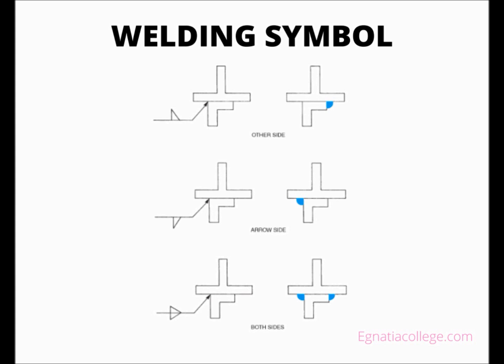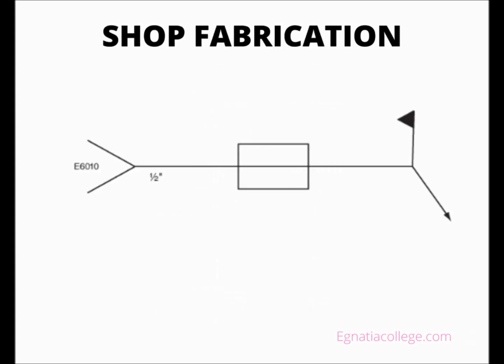Shop fabrication. Many structural subassemblies are more easily or more accurately fabricated in a shop environment. For example, if a special beam is to be installed with a welded subassembly on its ends, the subassembly would probably be fabricated in the steel shop so the beam can be delivered to the site ready for erection. A large structural steel frame might require as many fabrication drawings, sometimes called shop drawings, as structural drawings. Usually the field contractors do not deal with shop drawings, and they are not covered in this book.